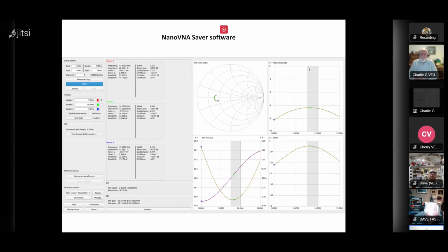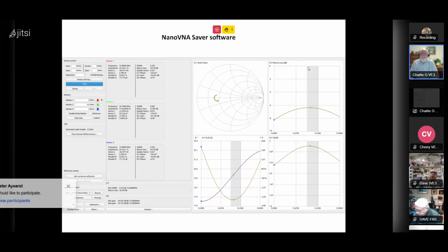Okay, yeah, thanks. The other thing is, when we did this for the probe design, and we used the NanoVNA to measure impedances, one of the things that I noticed was that although you can set up the H4 to measure 400 points, this thing only allows 100, which I wondered about. I would have thought you'd be able to set up 400 points, but that's just another question I don't know the answer to. Okay, thanks. Yeah, sorry, I don't know the answer to that one either.